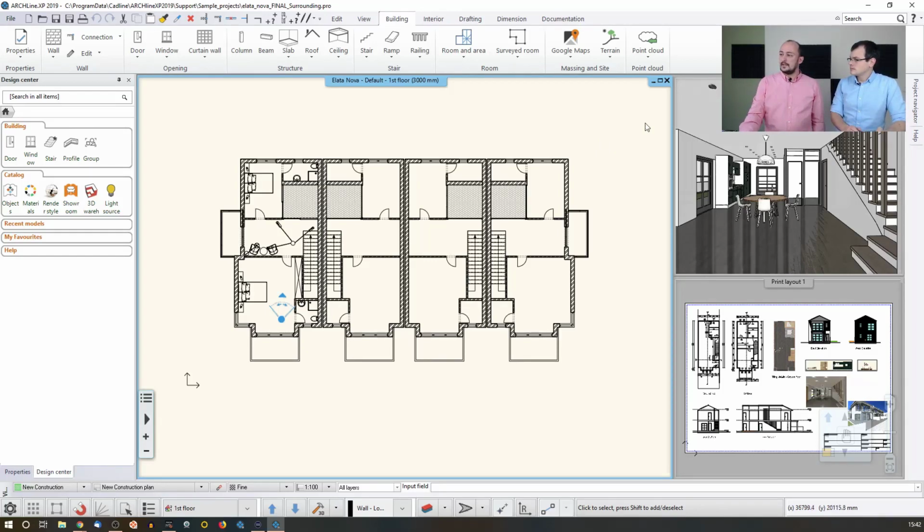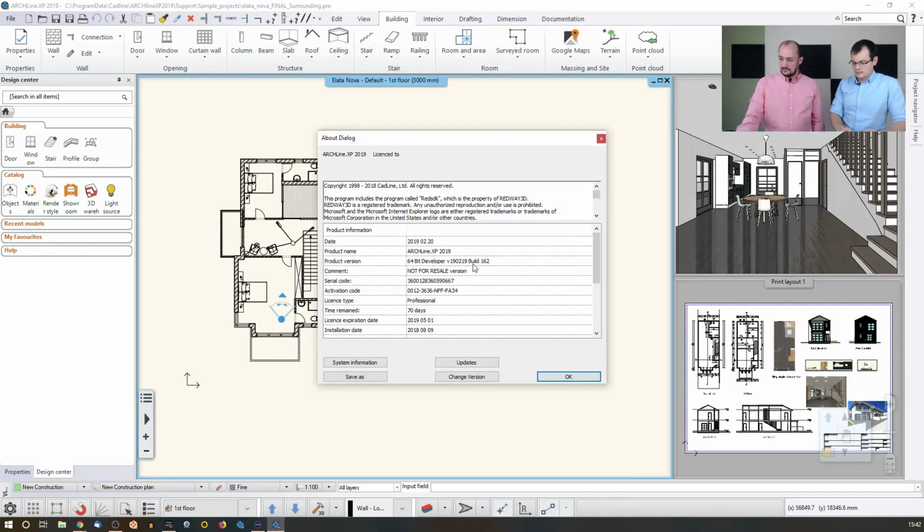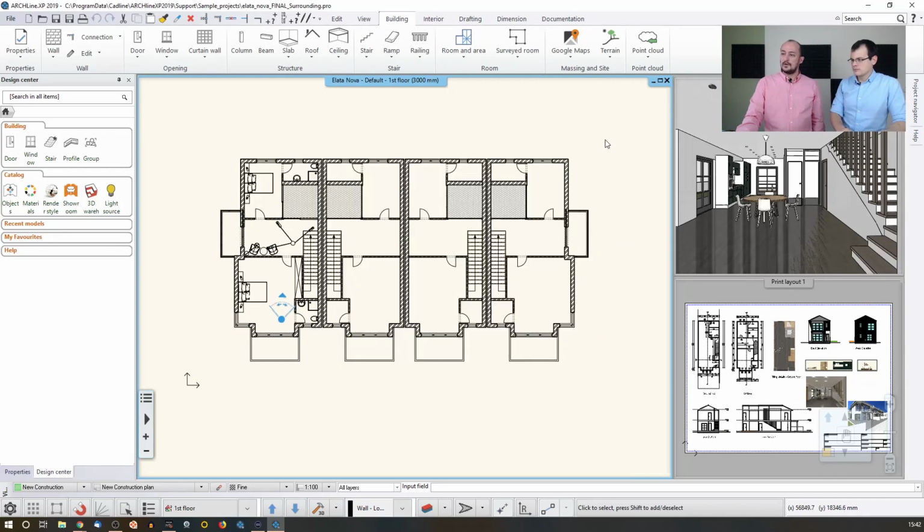And then you can just compare, if you're concerned that you heard there was an update, or you saw an email that there was an update, but the software didn't update itself. You can just go here and find About. You can see the build number, and then you can go online and see the installer and the build number. You just compare the two, and if you have an older one, a lower build number, then you just go there and download and install it.